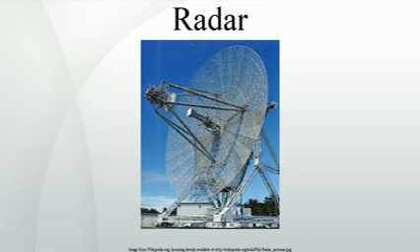Spoiled parabolic antennas produce a narrow beam in one dimension and a relatively wide beam in the other. This feature is useful if target detection over a wide range of angles is more important than target location in 3 dimensions. Most 2D surveillance radars use a spoiled parabolic antenna with a narrow azimuthal beam width and wide vertical beam width.